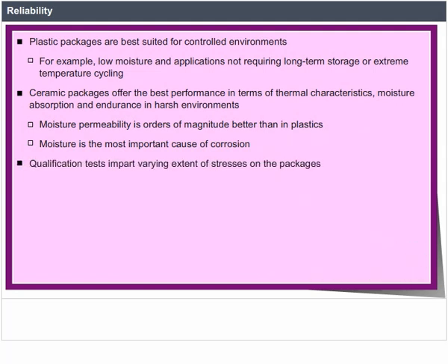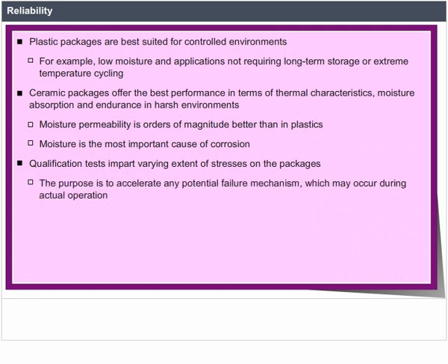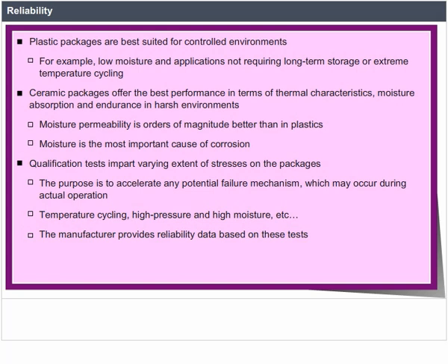Qualification tests impart varying extents of stress on the packages. The purpose is to accelerate any potential failure mechanism which may occur during actual operation: temperature cycling, high pressure, high moisture, etc. The manufacturer provides reliability data based on these tests. Fabrication process certification: QML, MIL-PRF-38535.